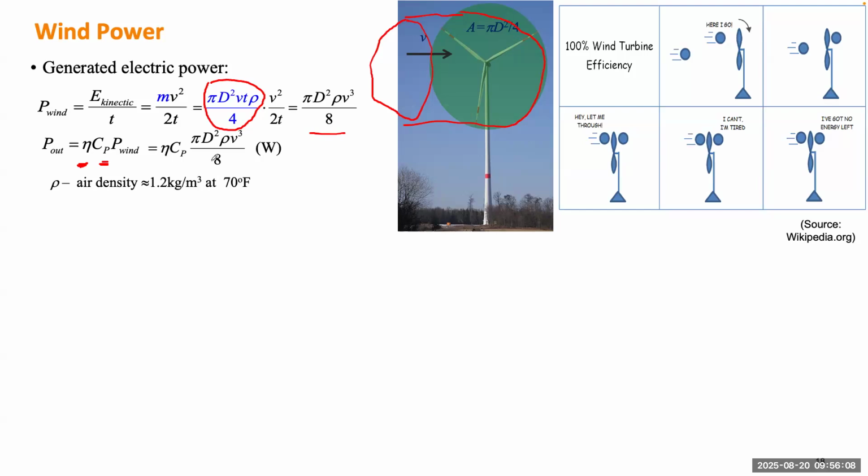So that theoretical limit usually is about 0.4, 40%. There's a theoretical calculation based on the Betz law. So the value is about 0.593, or around 60%. That is the theoretical limit, no matter how you design the wind turbine. But in reality, usually that coefficient is 40%, 0.4.